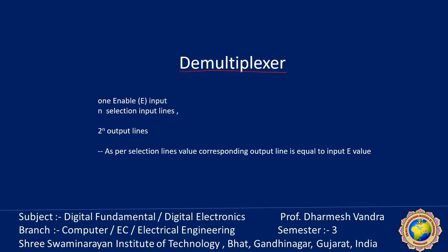As we discussed the decoder in the last lecture, some IC decoders are constructed with NAND gates. Since NAND gates produce the AND operation with the inverted output, AND plus inversion, it becomes more economical to generate the decoder minterms in their complement form.